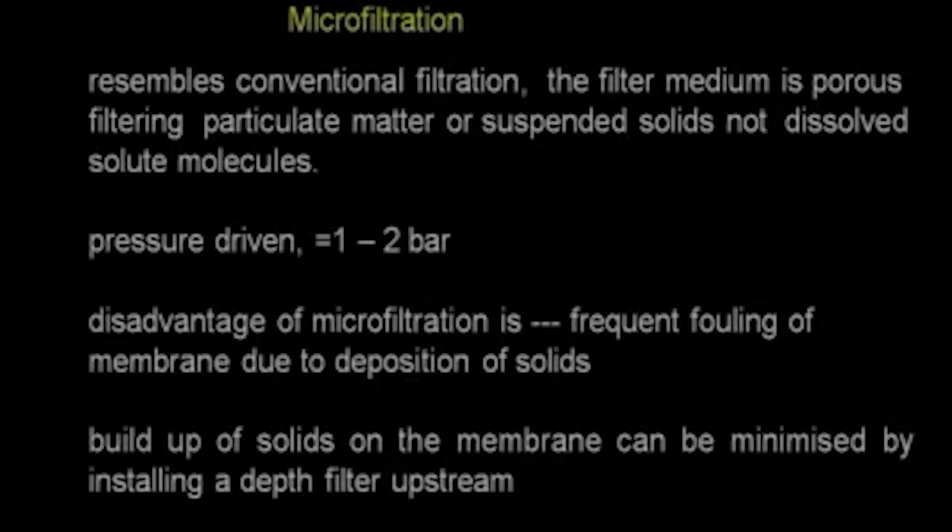We did talk about microfiltration some time back. Let me again recap on that. It resembles a conventional filtration. So there are small pores in the membrane material. So the solids which are very small will go through the pores and the remaining solids will get filtered out. So it is almost like a normal filtration process. Because there are pores, the pressure required is also much less. You use 1 to 2 bar. It is almost like the normal filtration where we also use 2 or 3 or 5 bar pressure. We do not go very high in pressure.